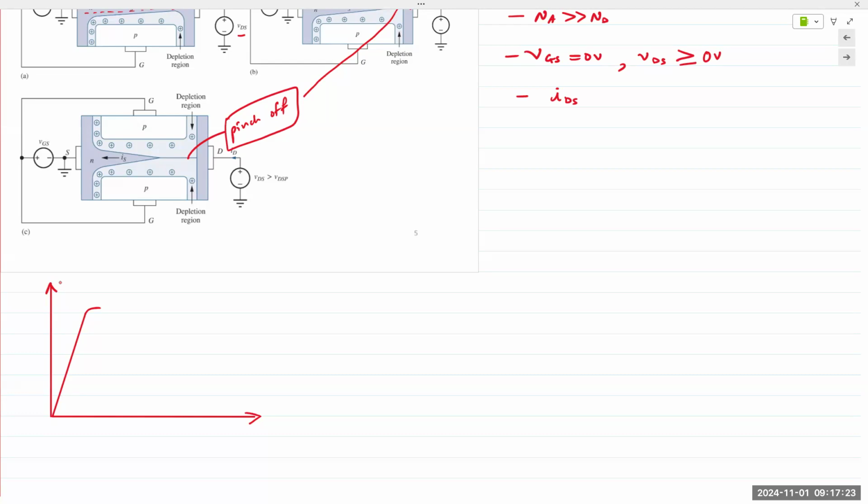However, what was noticed was that the depletion region, when it meets, does not quite pinch off the channel. So the term is kind of a misnomer. There is a small gap in there, and not just a gap. Electrons can also go through the depletion region and towards the drain and just move out. And so current flows through that gap. It reaches a saturation level, and the level does not drop. Okay, it does not increase, it does not drop.